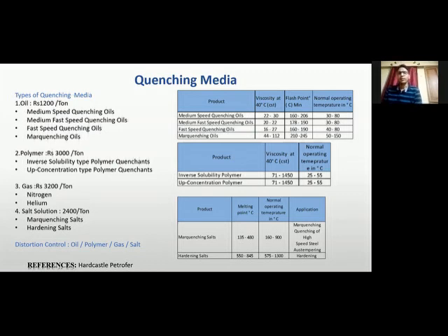Also, regarding polymer bath health, you have to agitate that polymer every 24 hours. Otherwise, bacteria will form in that polymer, and also the property of the polymer deteriorates. That will impact your final property of the component. That will be rejected or reworked. And also, after deterioration of the polymer, that will be scrapped, and the cost of that polymer will increase.